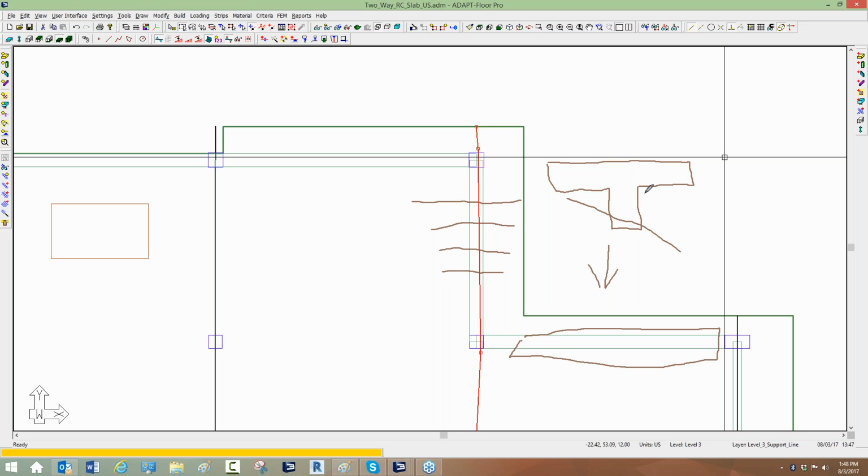It ignores the beam stem, and you get more rebar than what's expected because of that. So to bypass that, to always ensure that this happens, you use the waffle and joist construction. It's just a simple way to ensure that it's using the right section.